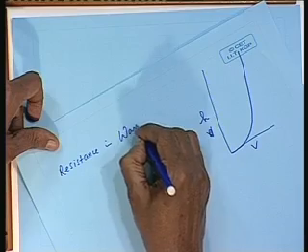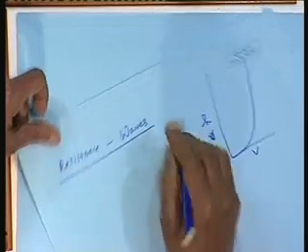The ship already has waves, it is not the ship's waves, the sea has waves and the ship has to negotiate the waves, then there is an augment of resistance called resistance in waves. Now, this is something which is not required in trial condition, because normally we will take out a ship for trial when the sea is calm, but in service this will invariably be there at sea.